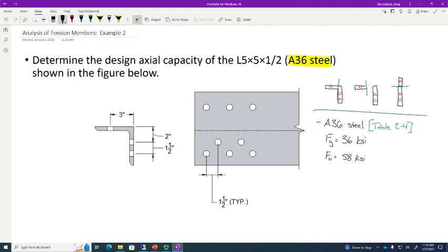A good example, how many of you have driven by the Innovation Building on 4th Avenue? I guarantee you those are A992, guaranteed. Because we aren't going to have to worry about that here. It's not a very large structure. I mean, it's not 30 stories tall. A992 grade for those W shapes any day of the week, and twice on Sunday, I guarantee you.